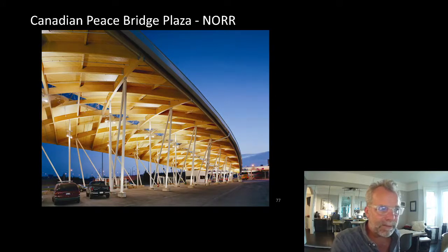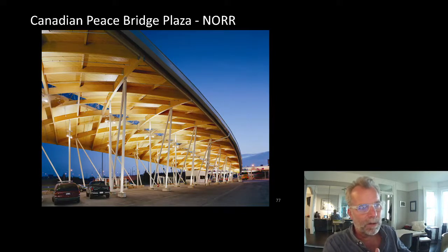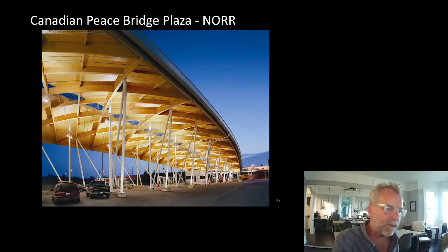Because of that, they have different demands on them. Because of budget constraints, we had to size according to the demand to minimize the amount of wood fiber in the project. And in the end, it winds up with this kind of extraordinarily beautiful argyle pattern of light and heavy diagonal members. It was not intended in the original design, but wound up being really effective.